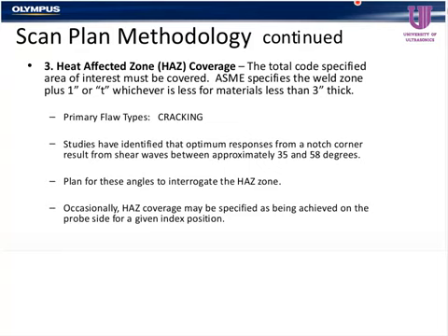To highlight that a little bit better, this doesn't mean that you can't use anything above 58 degrees. We're not trying to eliminate the higher angles from interrogating or evaluating cracking. We use these particular angles because they best reveal a surface connected defect, which, if we're trying to look for or determine surface breaking cracks, we would want to make sure that we do position those correctly.